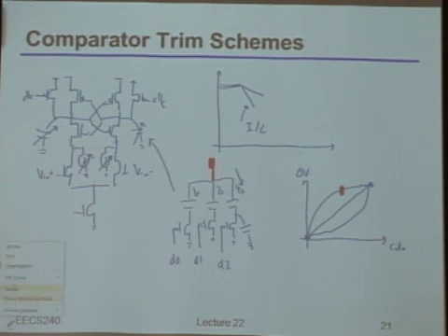And by the way, just to be totally clear, the way you might build something like that, just as an example, would be you take a bias voltage, and then you either feed that bias voltage to the gate of a transistor that you're going to use as a current source, or you ground the gate. And then you take a bunch of these and connect them in parallel, meaning you tie the drains of all those current sources together. And that, of course, would be your output current.